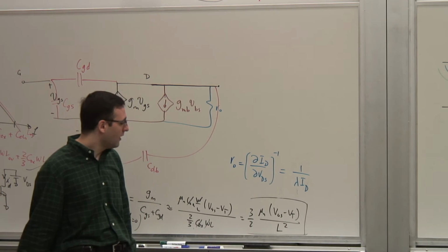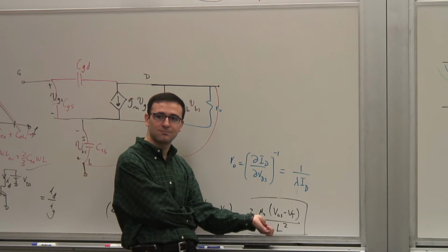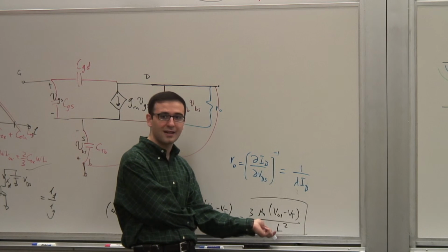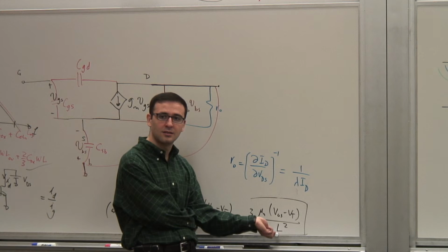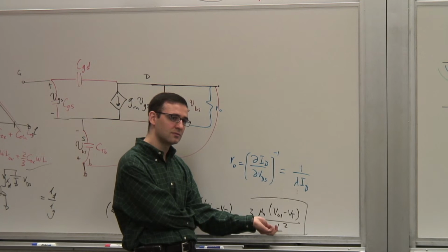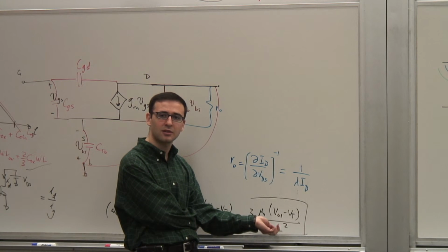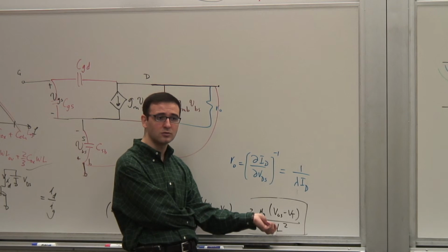Right, fine. Now, perhaps the most interesting aspect of it, which gave rise to all of this scaling stuff, and we talked about it qualitatively before, is this. If you halve the length of the channel for a non-velocity saturated transistor, your cutoff frequency quadruples.